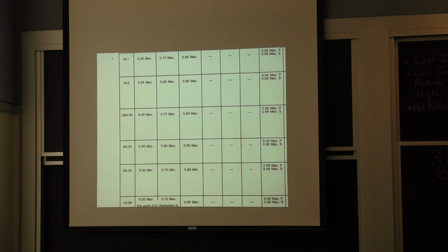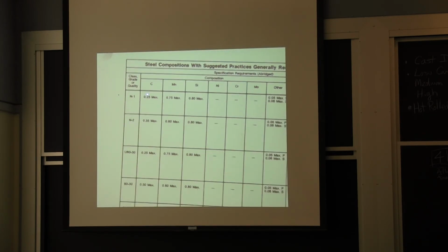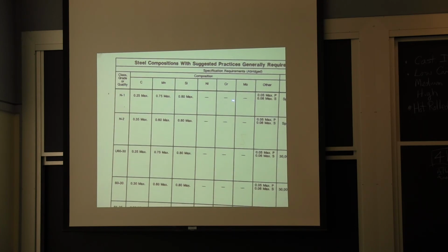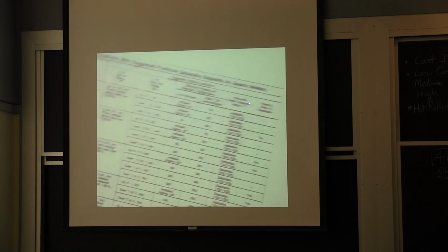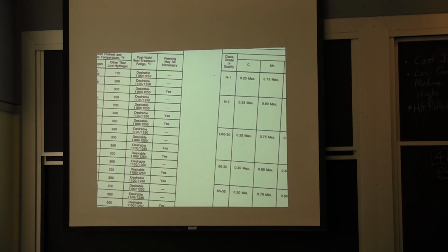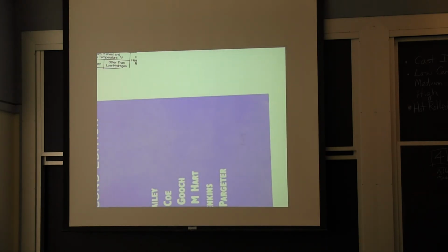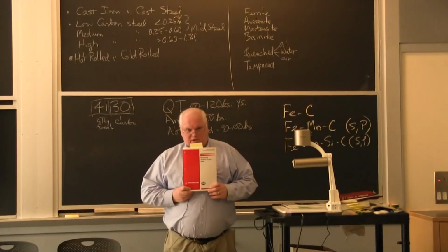It will also go across and tell me what the spec says the composition of that grade of steel should be and things. So that one little table, and about 10 years experience as a welding engineer, and I can draw up a procedure as required by some book such as the Structural Welding Code.